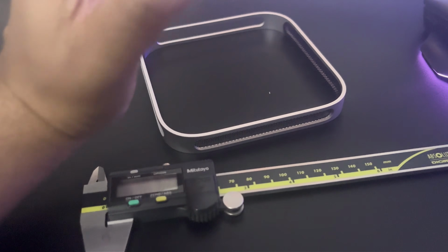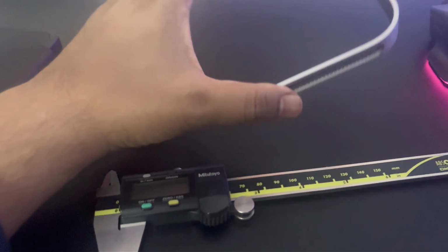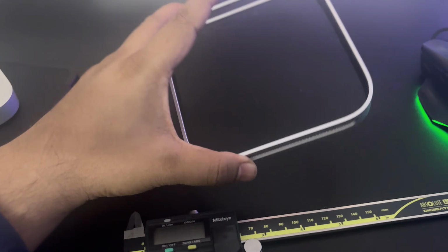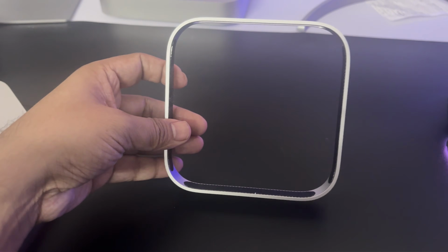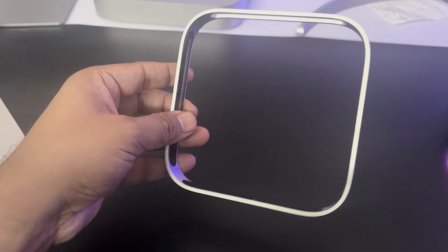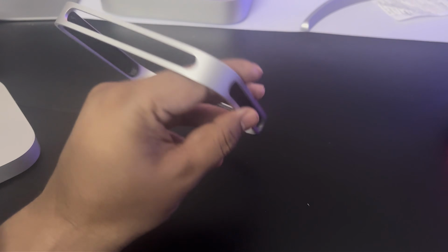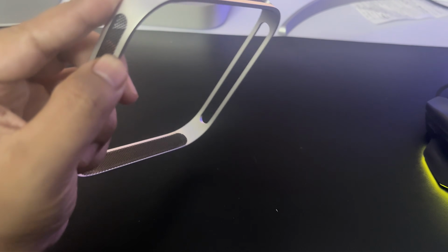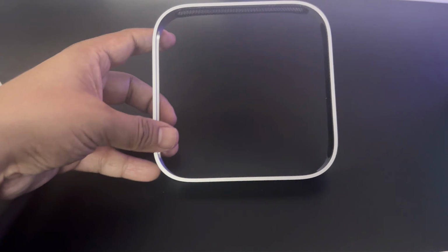Alright, since so far we have only covered pad and pocket, I am going to use Sketcher, pad and pocket to create this geometry. I am going to start by analyzing the shape of it. Here we see a rounded square shaped geometry, and of course this is a thin shell, and then there are cutouts in all four areas. Apart from that, if I talk about the chamfer, there is a little bit of roundness available all across, which could be 0.2 mm. So that also can be added to our design.